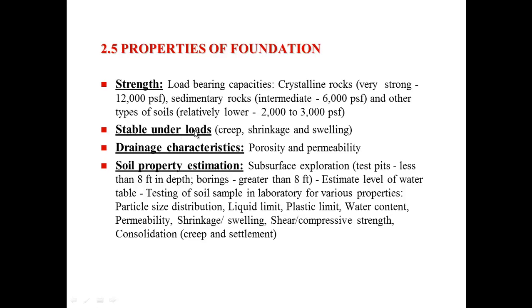Stable under loads. There's things like creep, shrinkage and swelling. Concrete will shrink and swell as it cures. It will move. So even though it has a lot of tensile strength, it doesn't have a lot of compressive strength, I should say. It has a lot of compressive strength, but its tensile strength, its ability to stretch and move, make it less desirable, so it will crack.